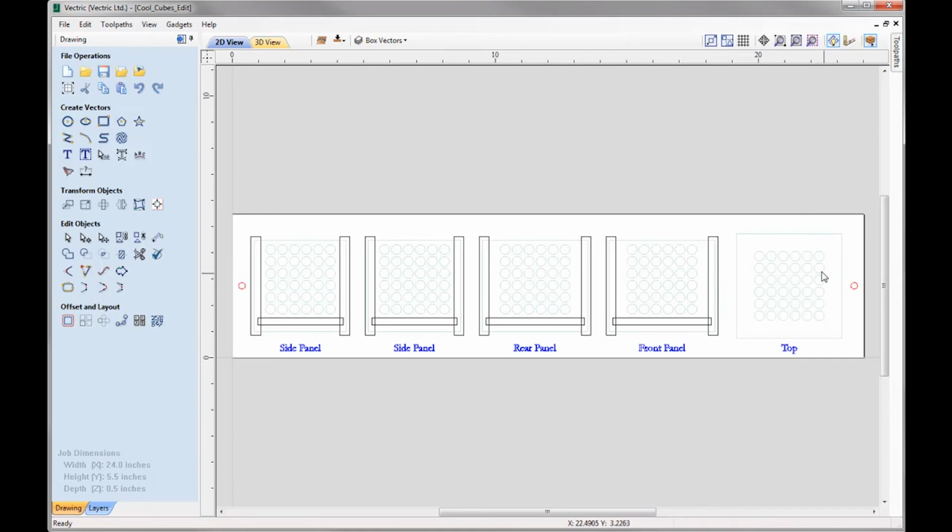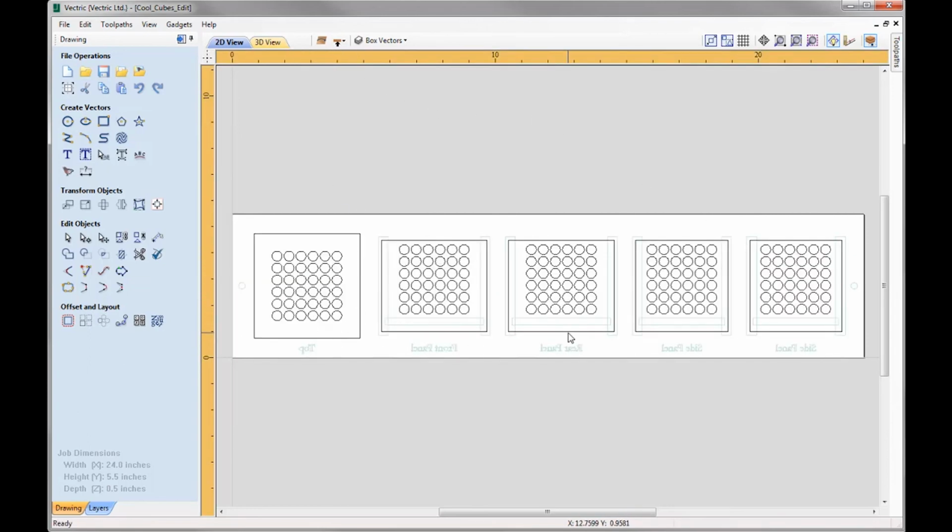We're going to cut all the way through the material and we're going to cut into the spoil board, where we'll then take our material off as we've finished with the top side, and then we're going to put the dowels into the spoil board. Then when we flip our material over, we're going to align it back in X and Y into the position, secure the part in place, where we'll then go and run the toolpath for the bottom side. I'll look at machining all of the decorative elements, followed by profile cutouts to cut all of these panels out. So let's go and run these toolpaths.